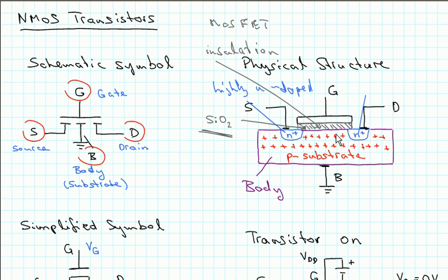And then on top of it is the gate. So this part here, this is the gate. Originally that was metal that was put on that oxide, or in fact it even consisted just of aluminum that then was oxidized on the lower side so that it formed an insulator. And in modern transistors, this is often made from polycrystalline silicon. Okay, so this is the gate. And so this corresponds to the four terminals that are shown over here.